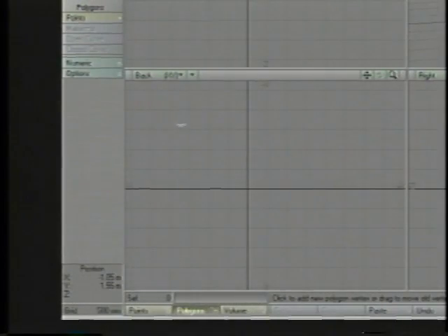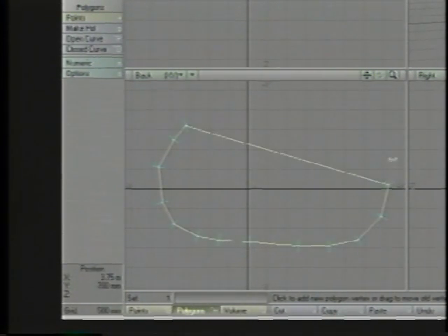If I start clicking the other way, go back and select the pen tool. If I click the other way, counterclockwise, I don't have to flip it, because depending on how I select the points and how I draw out the points, my normal will face the opposite direction. So it's actually facing at me now. Just an interesting note.